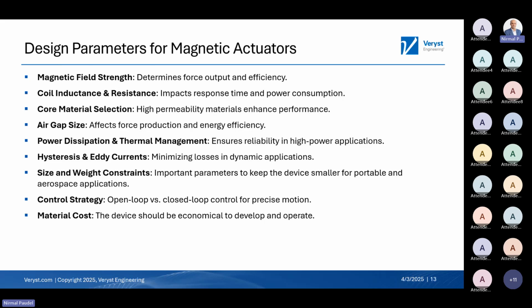Sometimes there are intentionally added gaps, but sometimes we try to minimize those to achieve the maximum force. There are hysteresis and eddy current losses. We have to minimize those. And then, as an engineer, we always have to be mindful of the size and weight constraints, and also the material costs.